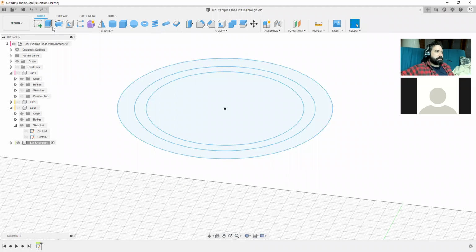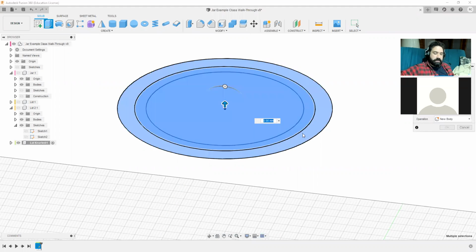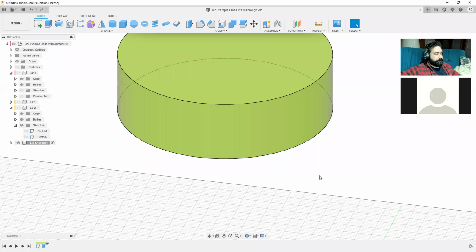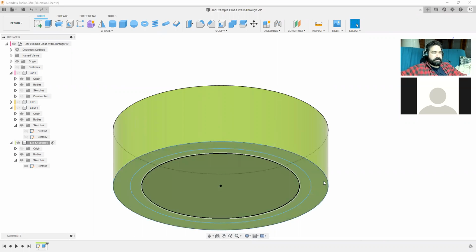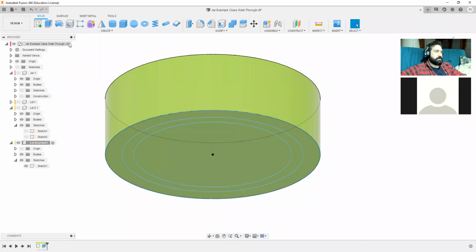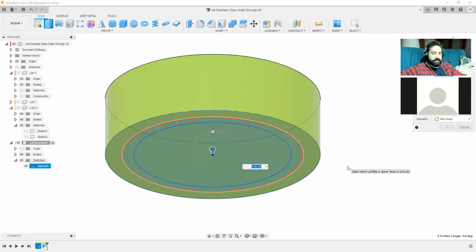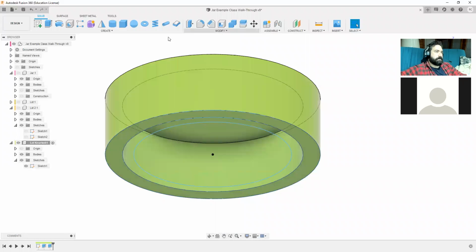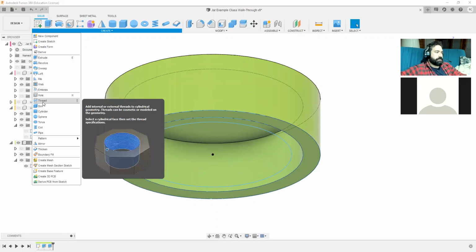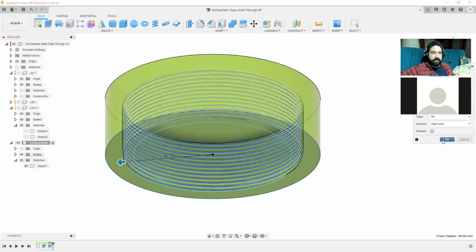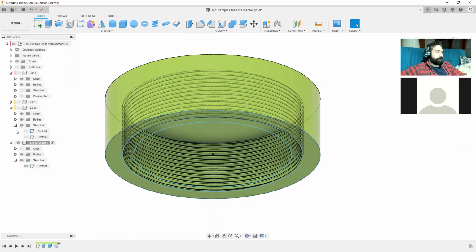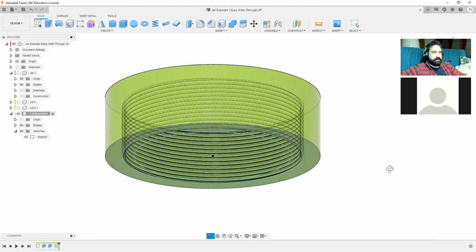Finish that sketch. Extrude the hole to do up to 22. Doing the same. I don't necessarily need to make the threads in here, but just for accuracy's sake. Extrude up and in. What was it, 19? Yeah. And then go through, thread it again, automatically select 63 millimeters or M63 1.5. Make sure that it is modeled. Hooray. All right. So right back to where I was before.